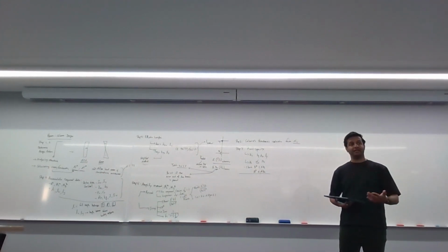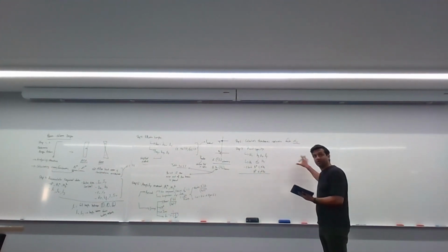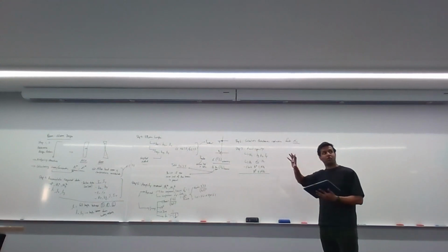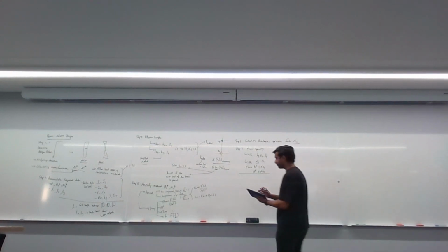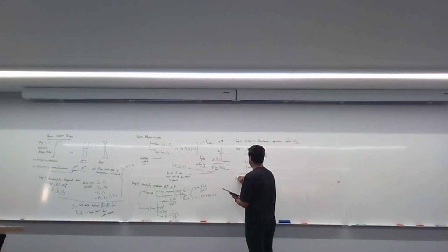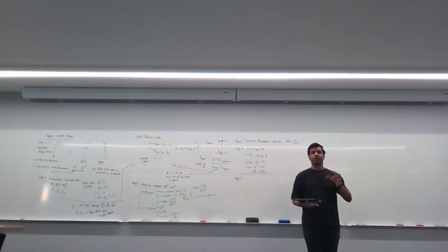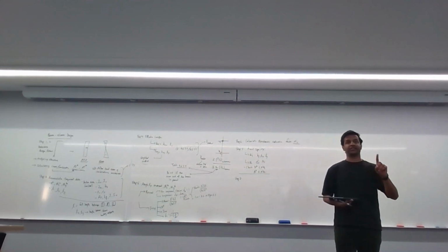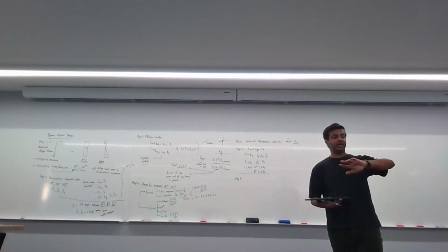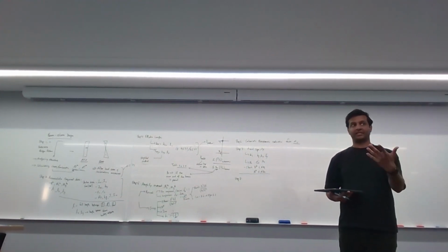You also have bending. So the next stage of your calculation is going to be all the bending related stuff. Now let's do step 8. For bending, there are 2 strengths that govern. The first strength is your section capacity for bending, and the next is your member capacity for bending.